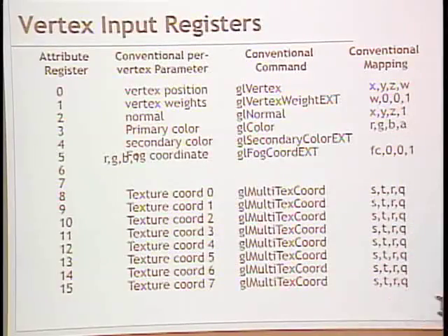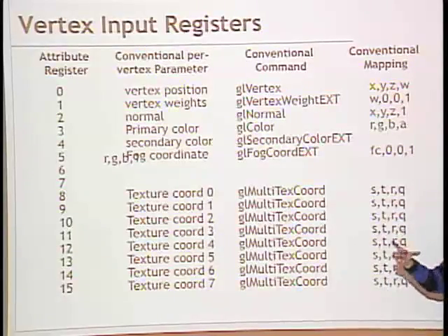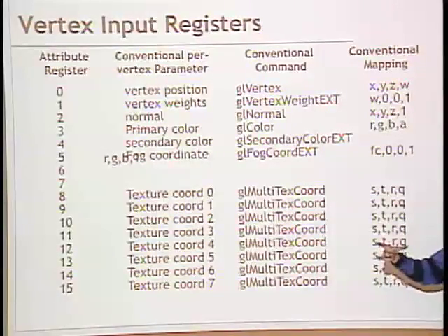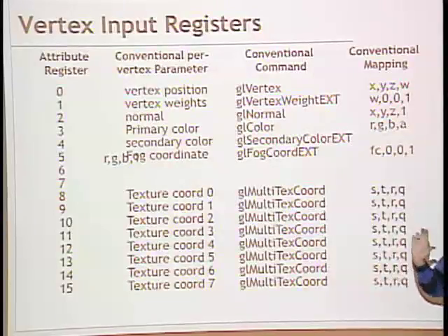This immediately makes it a little bit different than what you see in a microprocessor. A microprocessor usually has something that's 32 bits wide. That's how wide its data path is. This processor is 128 bits wide, and it does partitioned 32. It does 32 times 4 vectors. A vector that's 4 wide.